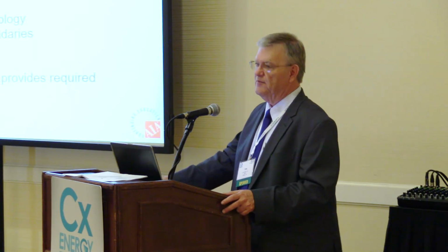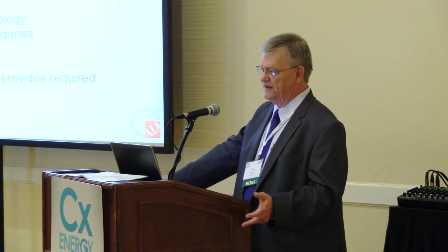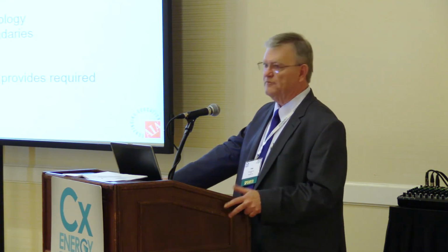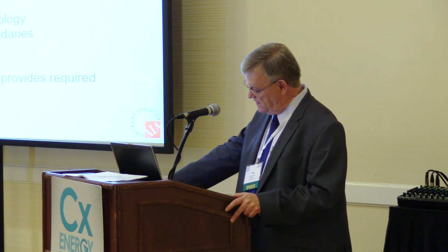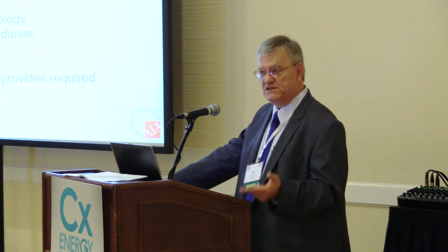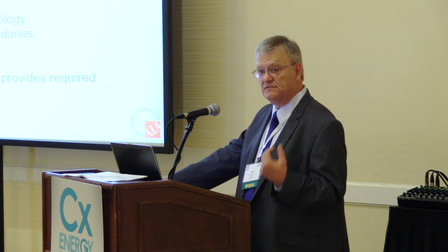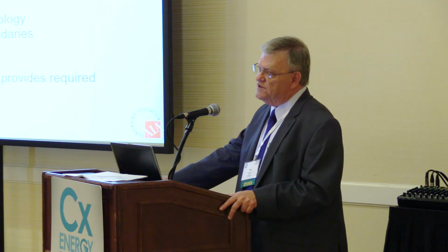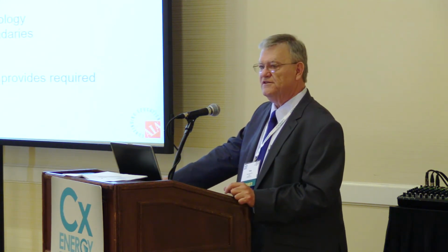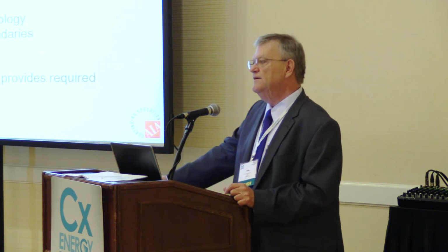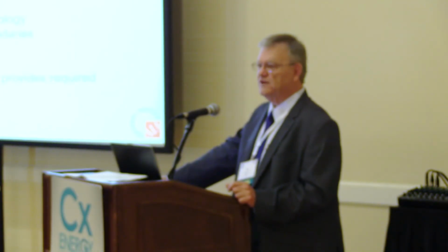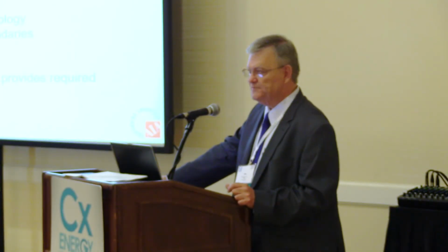We'll need to come up with a strategy for how we test things like daylight harvesting, and we need that in advance. That'll probably lead us as designers to specify that a test plan comes with the submittal for the equipment. Engineers can sit in our offices and think of clever ways to test lighting systems, but anybody who's ever done it knows that schemes that were cooked up by eggheads in air-conditioned rooms often don't work exactly as well out in the field.